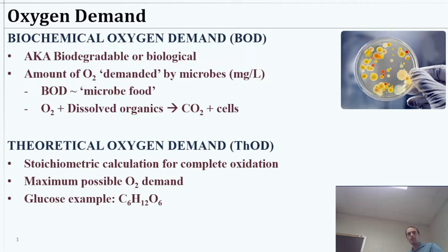Then the BOD is essentially that food that the wastewater treatment is supposed to remove. And the mechanism here is respiration, right? Oxygen plus the dissolved organics makes energy. We oxidize. We do this ourselves. We breathe out the CO2. And the microbes will also be making new cells.